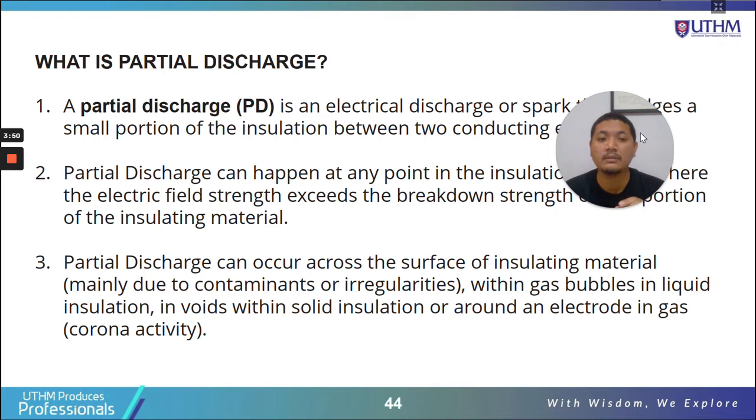Voids are basically air pockets inside the solid insulation, probably from a manufacturing defect. So there's a void or air pocket inside the solid insulation, and because of that, partial discharge can happen in the void.